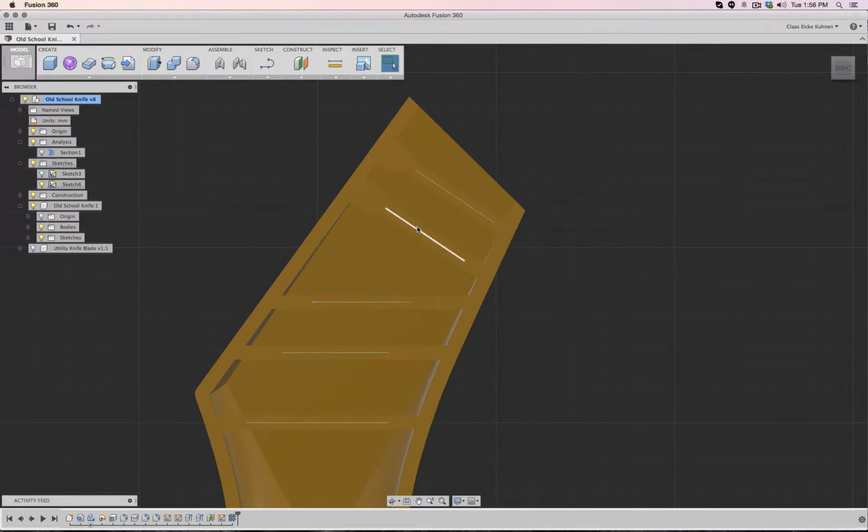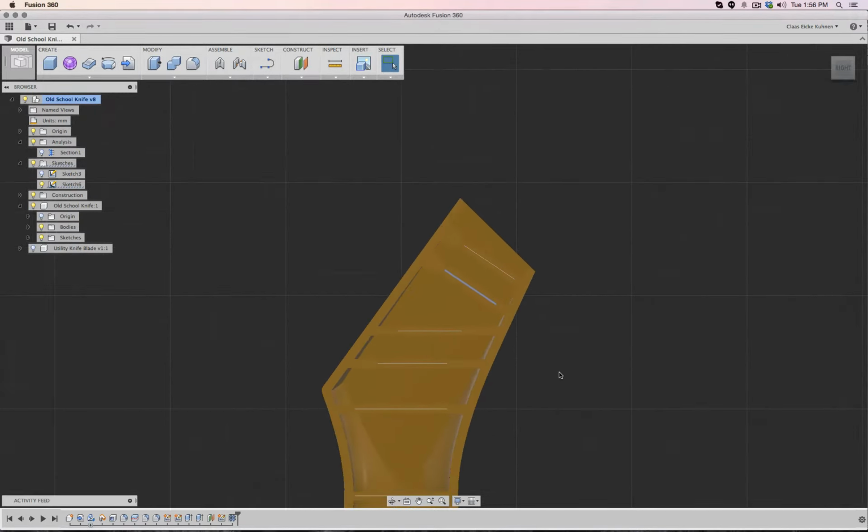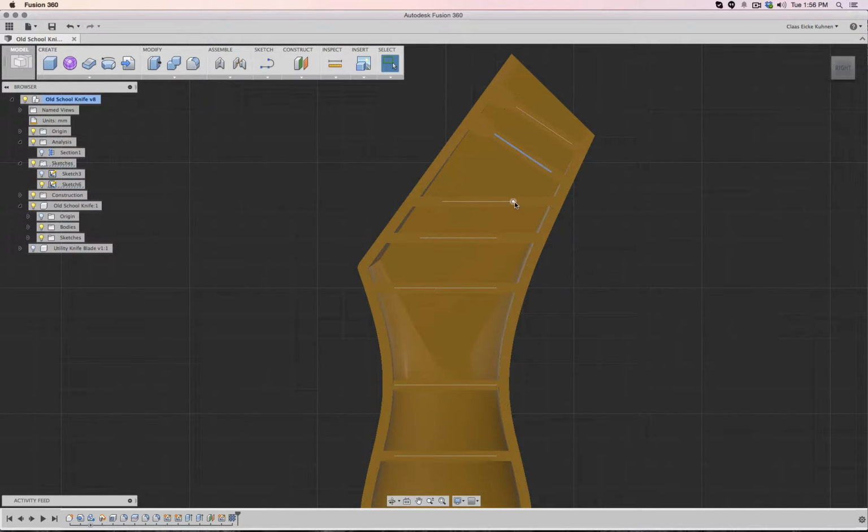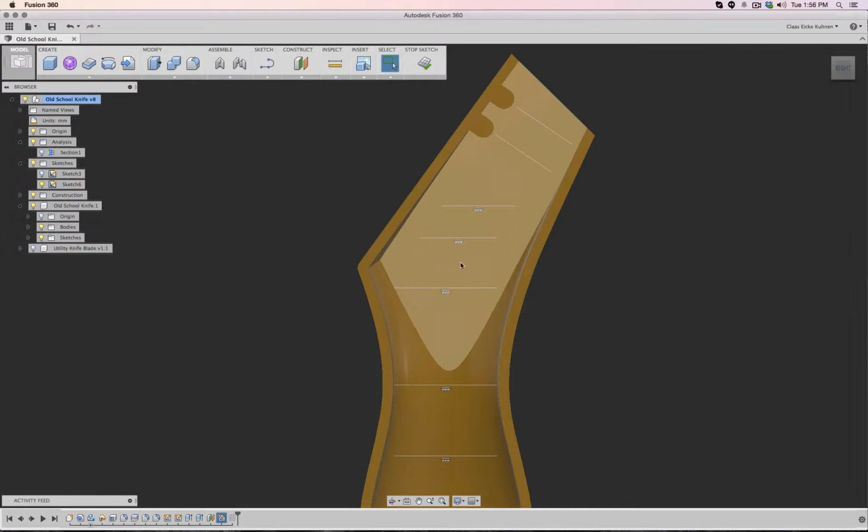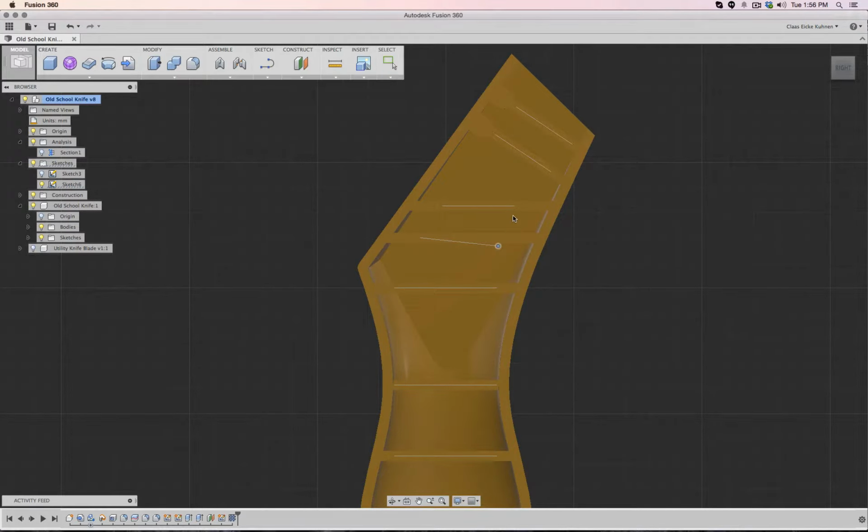to it, but I can click on those sketches and I can even, for example, here, well, this one has a constraint, so I can't really rotate it. So, but hold on 1 second. Let's go to edit sketch, and for all those, for example, I delete the horizontal constraint. Let's go back, and there you see I can rotate it. And I have to say, this is a really nice way to work.